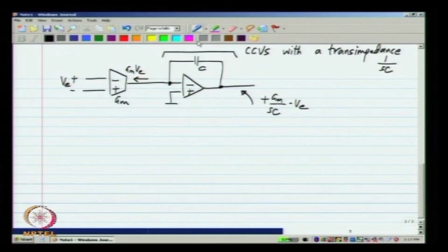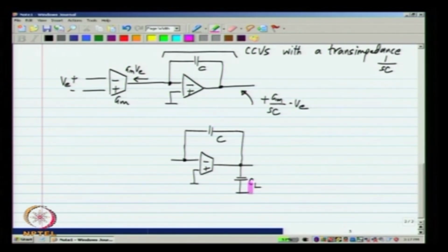So, if we do that, what do we get? This is the op amp used to make the current controlled voltage source. And I will call it CL. CL will be any capacitance that is loading the transconductor plus any external load that may be applied to the op amp. Okay. So, that will always be present. So, all of that is clubbed into a single capacitor CL.